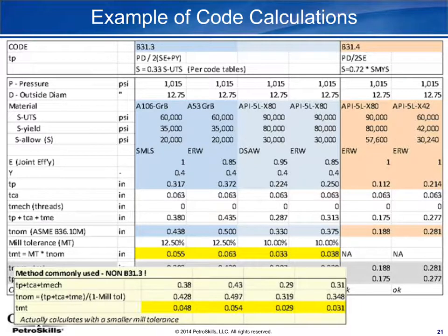So because we usually care about how corrosion resistant stainless steel pipe is, that's why we're buying all that chrome in that stainless steel pipe, we spec a low carbon 304L, which is below 0.03% versus below 0.08% carbon, and as a result, the strength of that flange will drop.